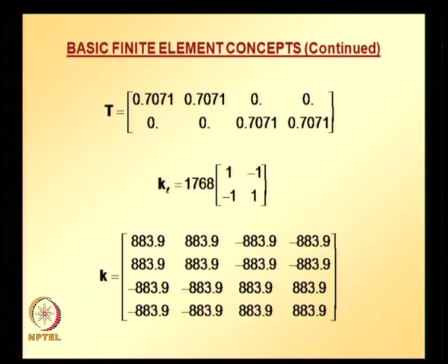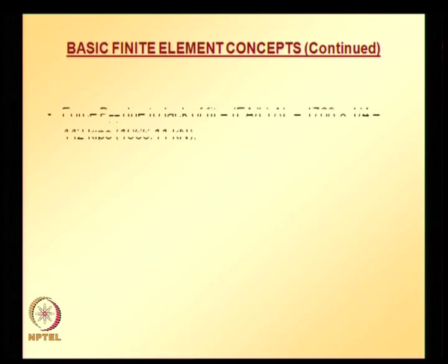And this member 1 is short by length 1/4 inch. So, the force P of t due to lack of fit we can calculate for this member as E A over L times delta L. Delta L is 1/4 inch, all are in inches. So, 1/4 is substituted, that is 0.25, and it is calculated. The value both in FPS units and SI units in kilonewtons are given there.